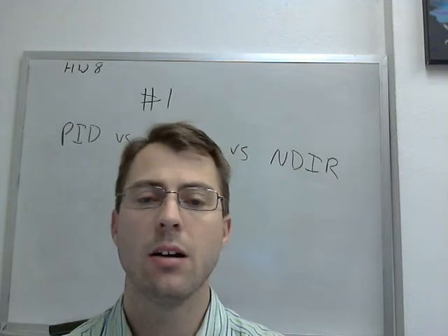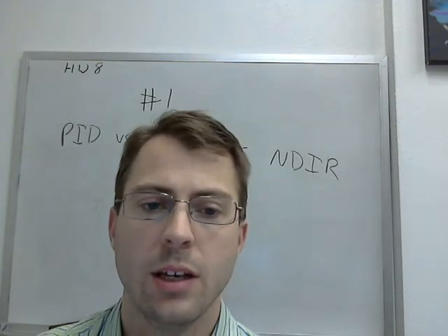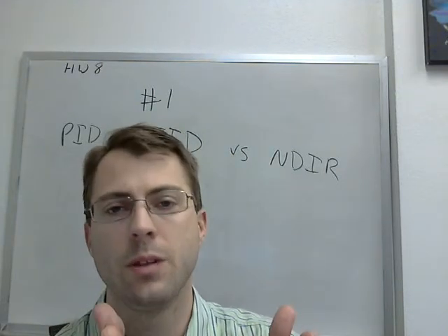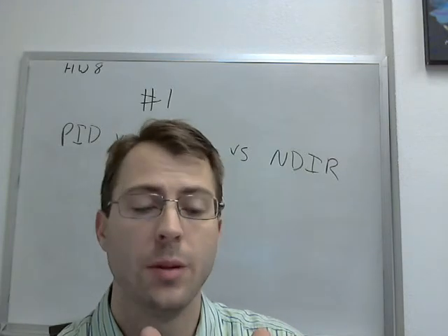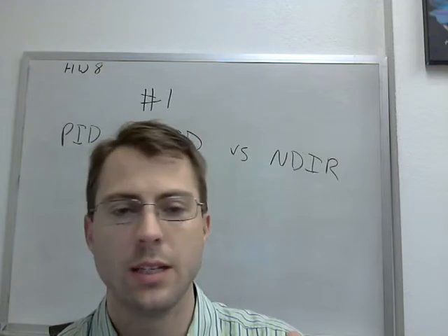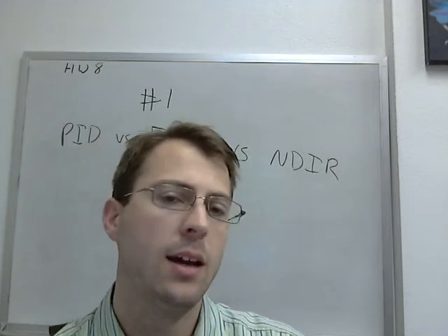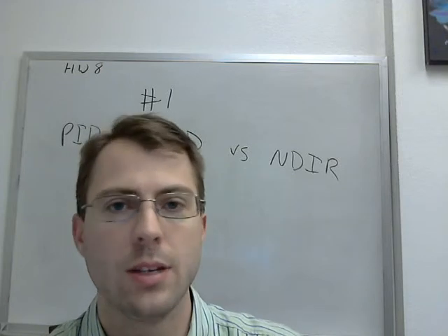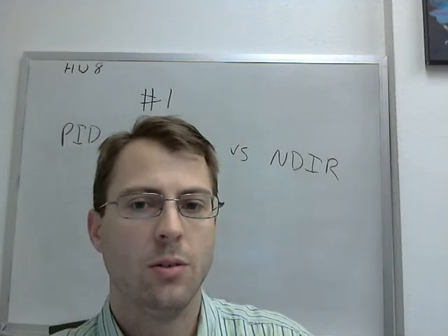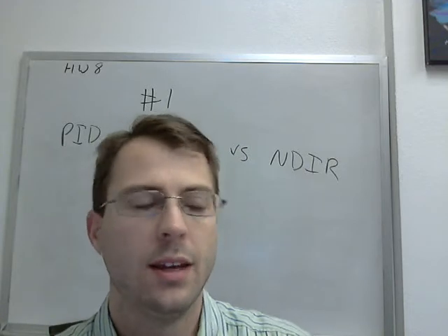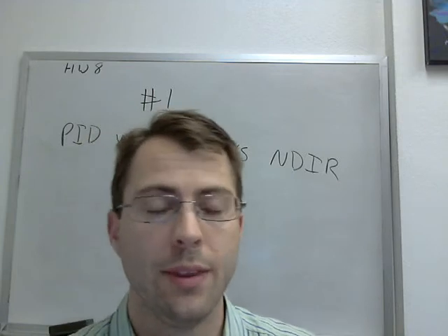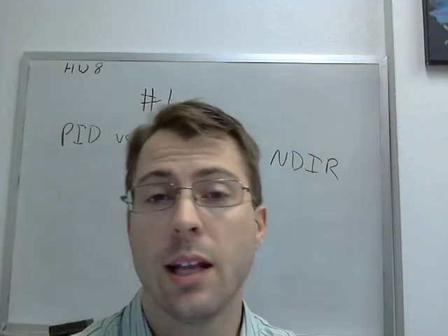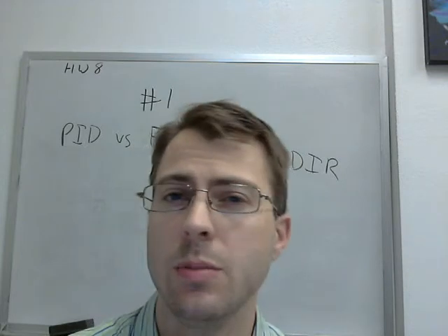And then an NDIR, non-dispersive infrared detector: basically you shine infrared light down a reference path that's sealed from the environment and down a path that is exposed to the environment, and the same infrared beam is being split and bounced back and forth between the reference path and the environmental path, and then it's being alternately routed to the detector, and so the detector knows the signal that's coming from the reference path and the signal that's coming from the environmental path, and it can calculate what the concentration is based off of difference in absorption.